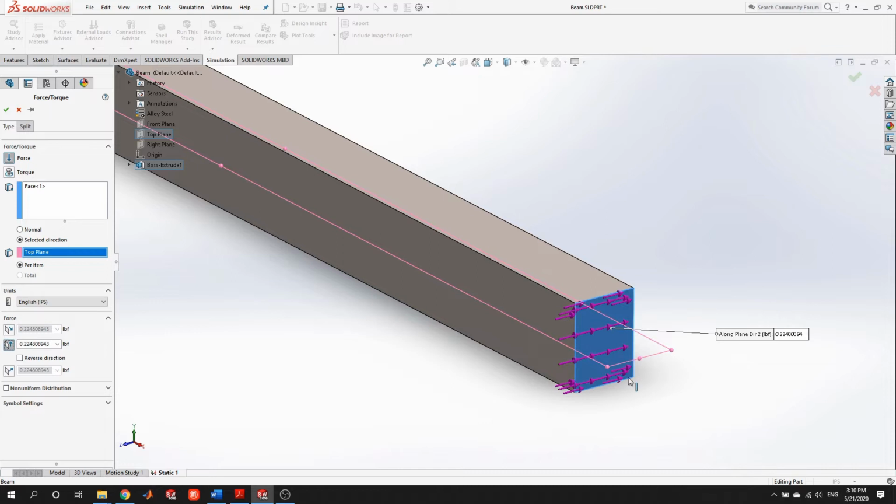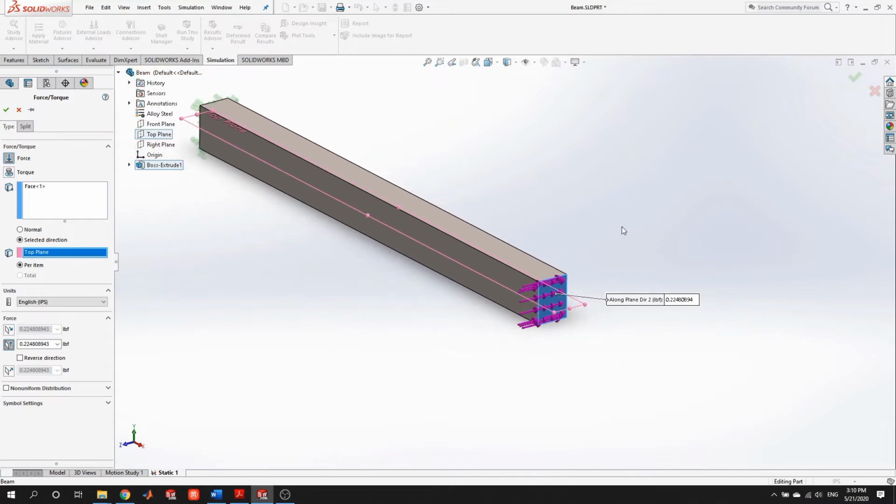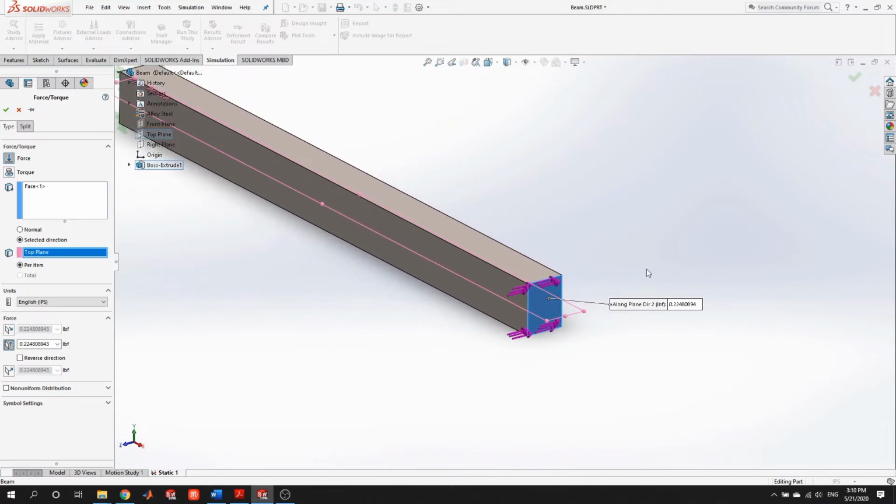We could give it this one, which is sliding across the plane. Now, this could be a way to load the beam as a cantilever beam, but because of our cross section, and in the absence of anybody telling you the way you'd want to load this beam, what would be the most logical? You can think in general for bending members that you want the tall side of the cross section to be basically parallel to the load.